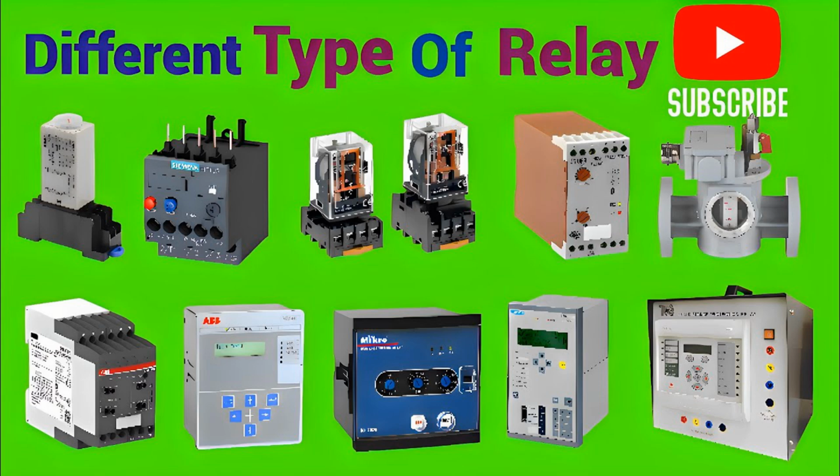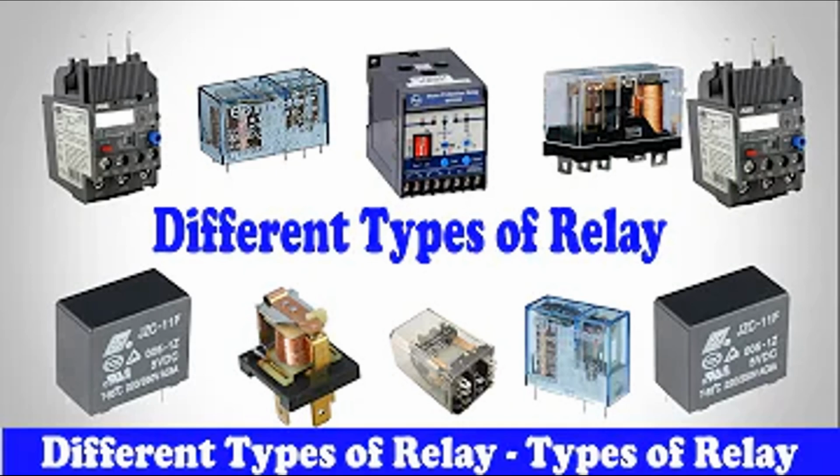Contacts. Normally open (NO) or normally closed (NC). Contacts that connect or disconnect based on the armature's movement and the current's polarity. Working principle. Current flow. When a DC current flows through the coil, it creates a magnetic field, whose polarity is determined by the current's direction.